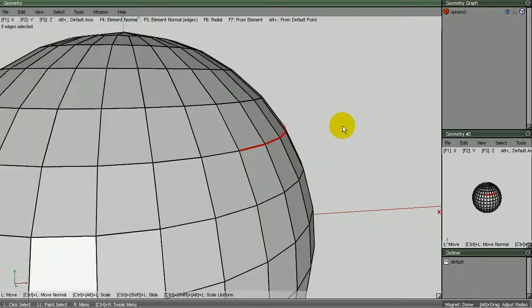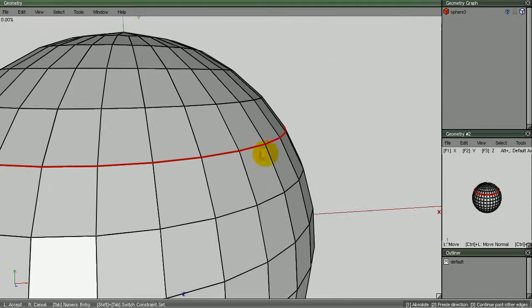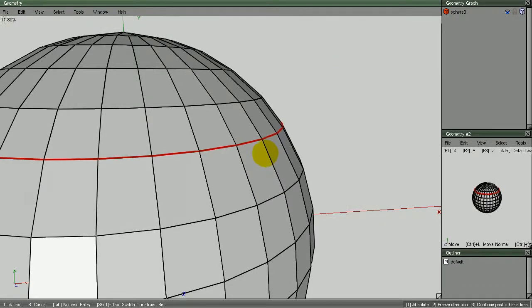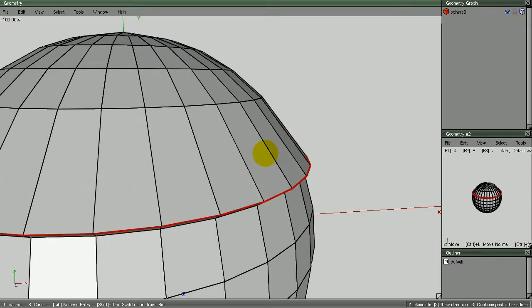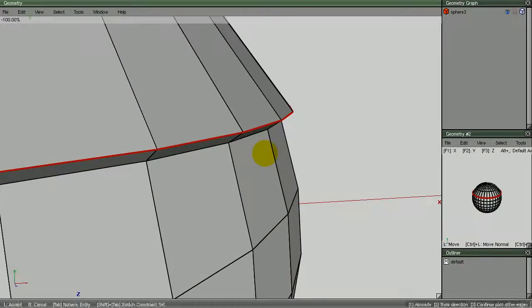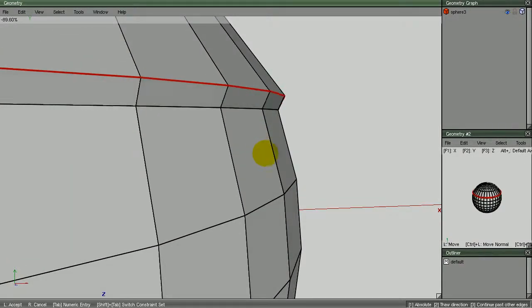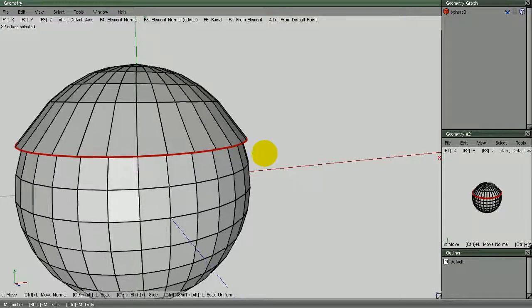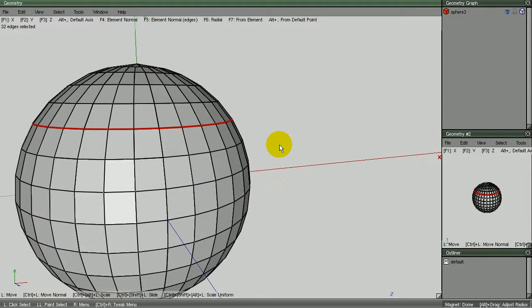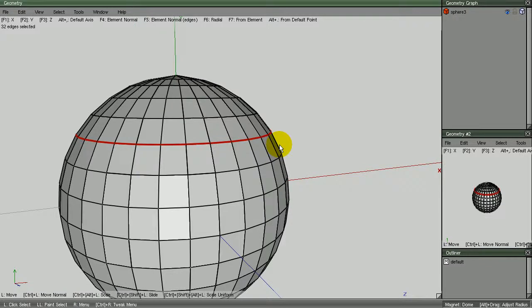So, if I cancel that, and I now just select this whole ring by holding down my L key, I can now slide this whole thing, freezing the direction so that it will create a lip or a ridge right over where I want to be. Right there. And again, that vertical edge is frozen. The direction of the slide is frozen. So that is the difference between frozen and thawed directions. That's the direction of your slide.